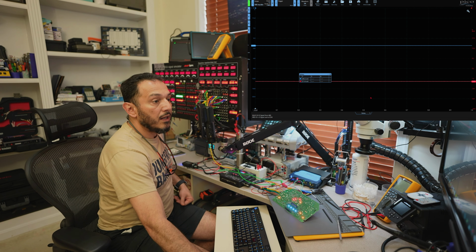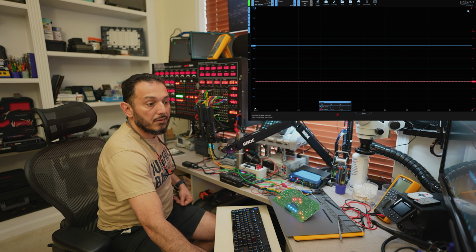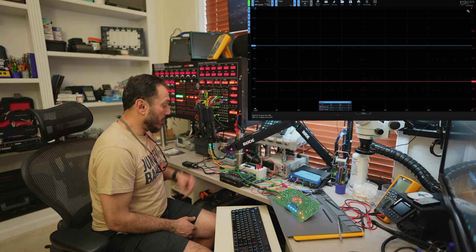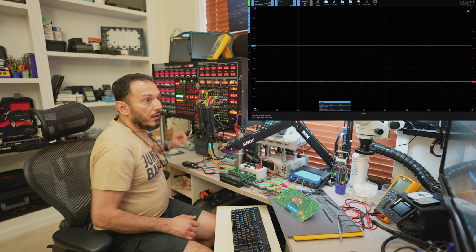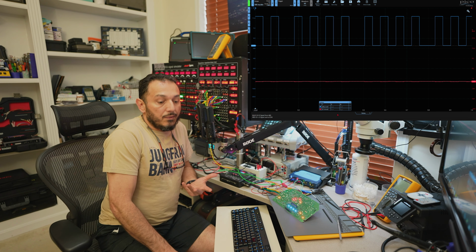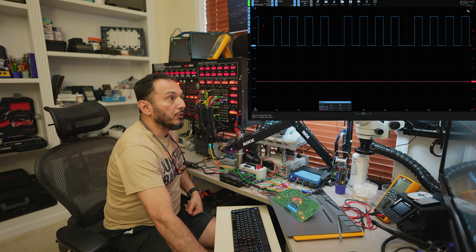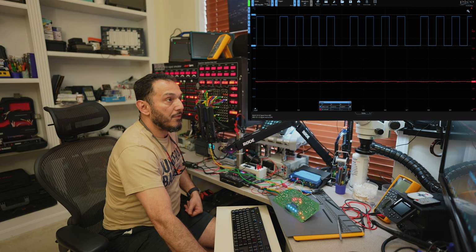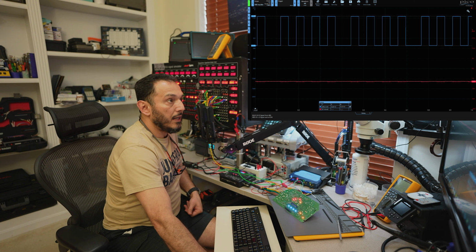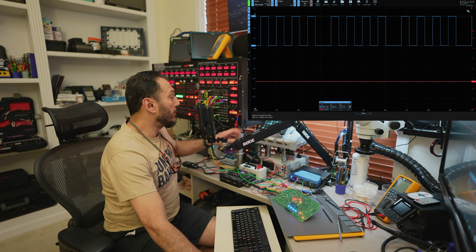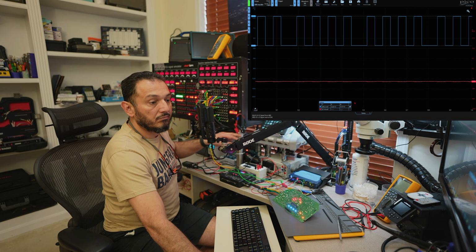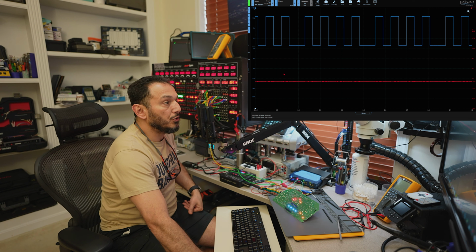All right, so I'm going to move this here at the bottom so it's not in our way too much. The first thing I want to do is inject the signal. So we can see now a signal on the blue channel. I'm going to put another cursor on the top of that signal, and that is the high part of that signal. You know what I'm going to do? Let me put measurements, and I'm going to do this with you so you learn how to do that.